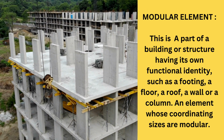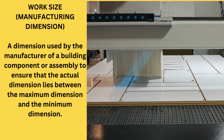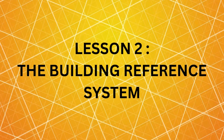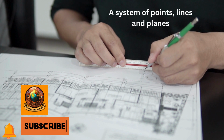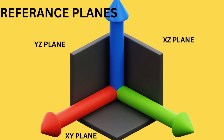Third, work size, manufacturing dimension. A dimension used by the manufacturer of a building component or assembly to ensure that the actual dimension lies between the maximum dimension and the minimum dimension. Second lesson, the building reference system. As architects and engineers, we have been using reference systems right from day one. It's a system of points, lines, and planes, on which the sizes and positions of a building component are placed, so like when we draw plans, elevations, sections, on the x-axis, y-axis, or z-axis. These are also called reference planes, so we have an XY plane or an XZ plane or a YZ plane.